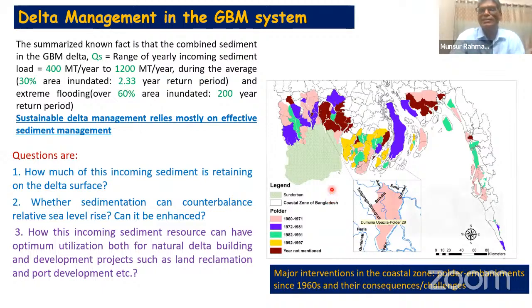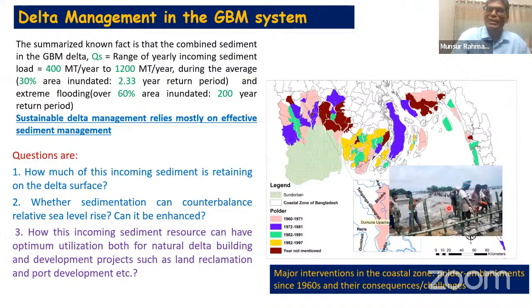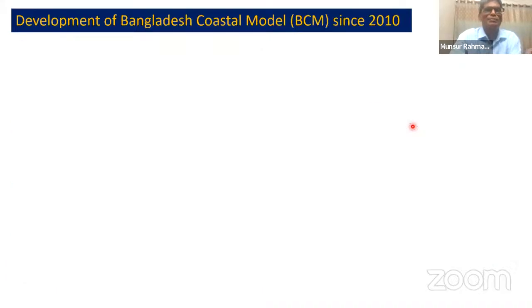These structures often fail, and then the water and sediment cannot enter inside right now. So differential sedimentation is happening outside, and differential land elevation is generated inside the polders. The land level is low. So any failure of this kind creates waterlogging problems, etc. So again, we have invited new challenges, and the question is how we can sort them out.